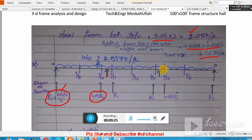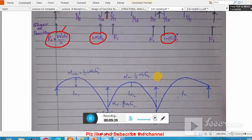And again the case will be repeated for the first interior support at the exterior face, with 15% more. Only these two shears are different; all the other shear values are the same, remember.